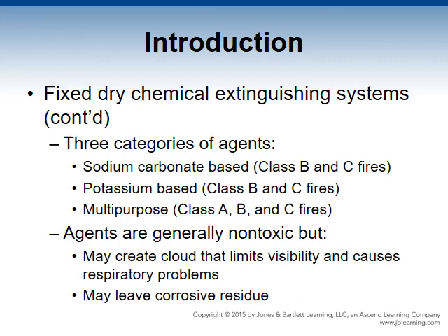These agents are not considered dangerous or toxic. They do not react with flammable gas and liquids, and they do not conduct electricity. Once discharged, they can create a cloud that limits visibility and cause respiratory issues. Some of these agents leave corrosive residue that can damage the equipment and components if not properly cleaned.